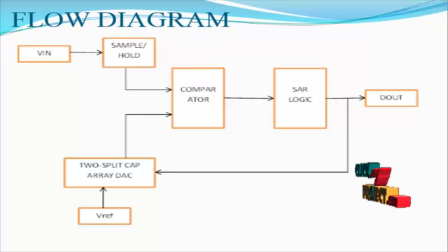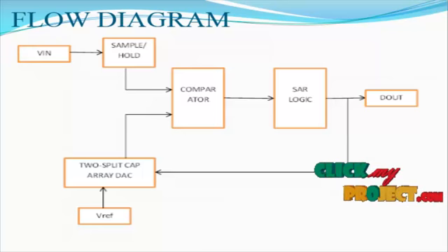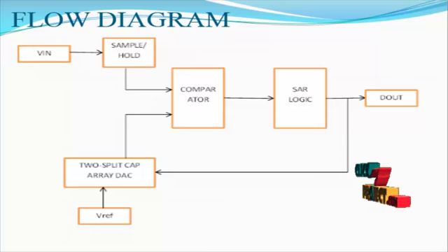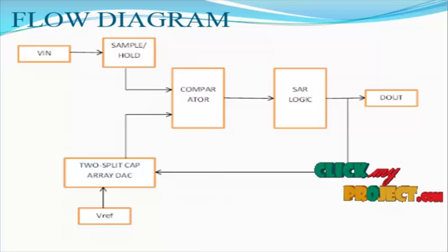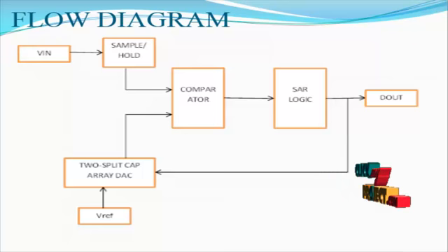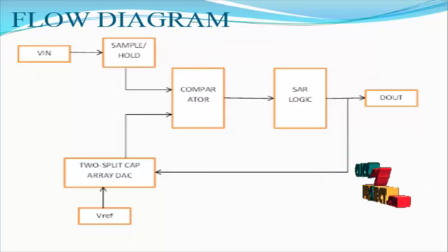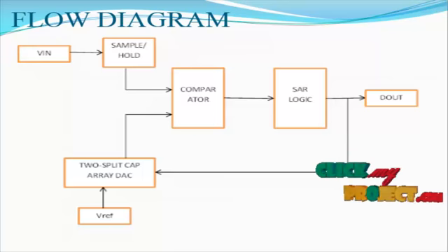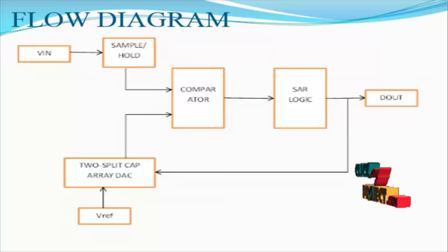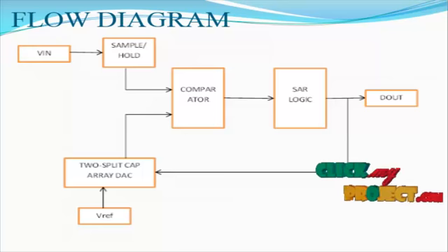The previous output based DAC signal is based on the selection logic: the V reference and ground signals are connected to the capacitor array and applied to the differential amp. To remove the losses for voltage reference and ground signals, it is applied with a two split array capacitor formation in the mux block. So the DAC block consumes the voltage difference output and applies it to the differential amplifier circuit. The amplified output signal is passed to one of the comparator inputs.